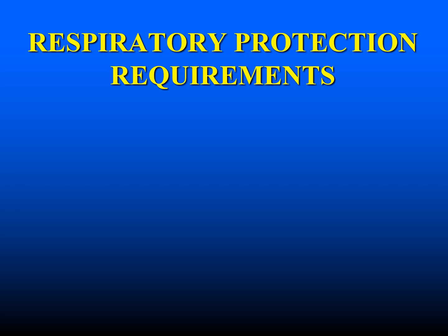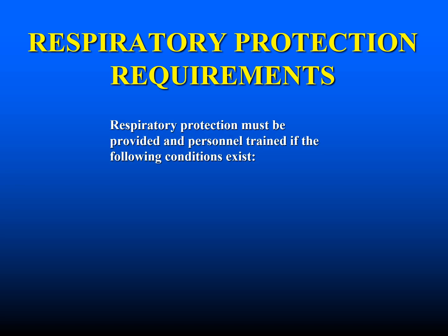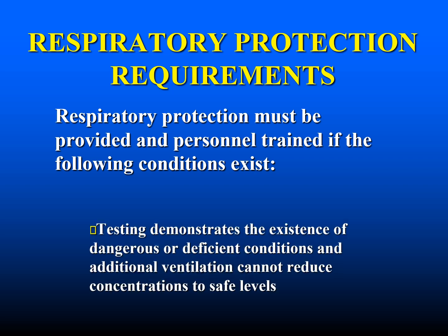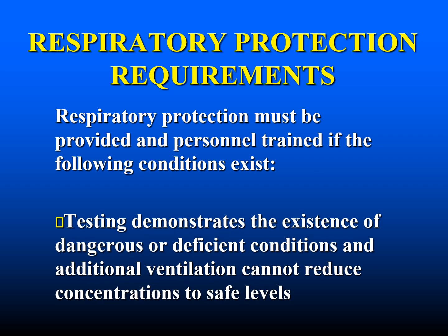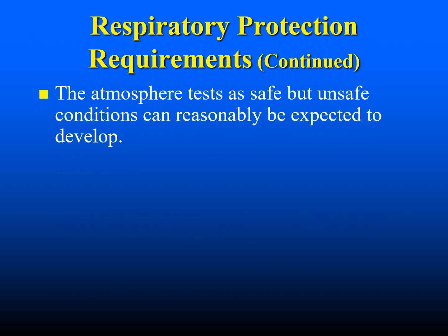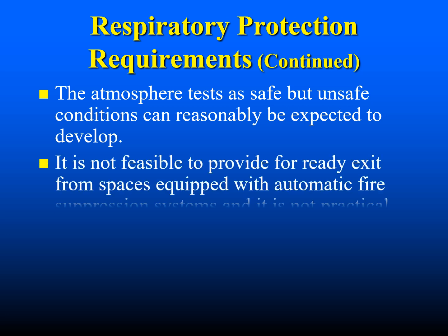Let's take a look at the respiratory protection requirements. Respiratory protection must be provided to trained personnel if the following conditions exist. Testing demonstrates the existence of dangerous or deficient conditions, and additional ventilation cannot reduce concentrations to safe levels. The atmosphere tests as safe, but unsafe conditions can reasonably be expected to develop.